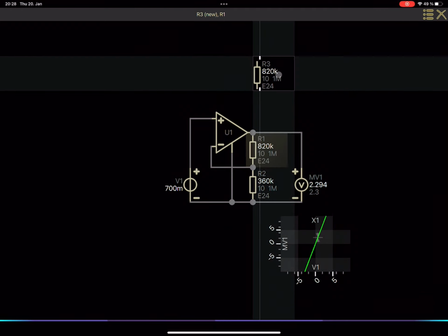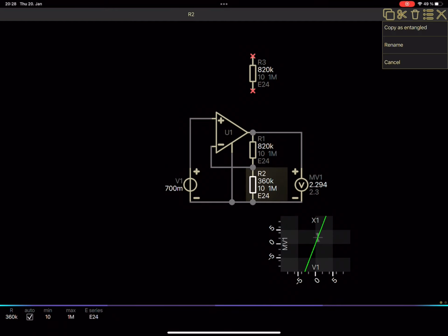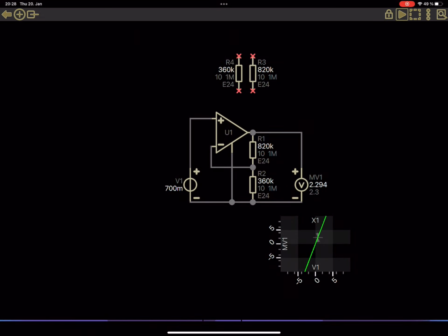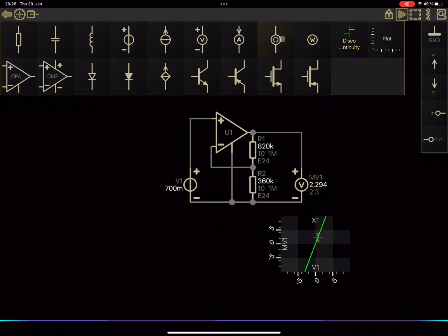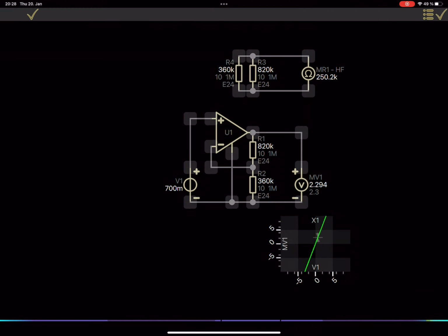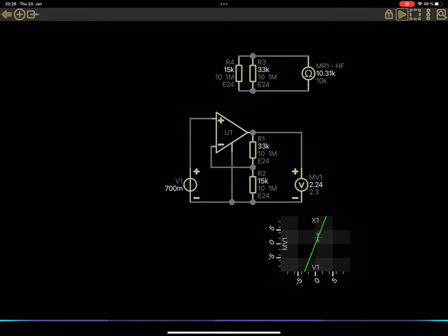Consider an entangled copy of a part as the same part, or a clone of the part, just used in another wiring context. All potential auto parts can be copied as entangled. Among many other things, part entangling allows us to create helper circuits for additional design constraints and target value specifications, as we do here to specify an inner resistance of the voltage divider used in the operational amplifier circuit.